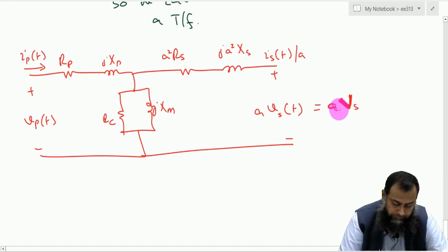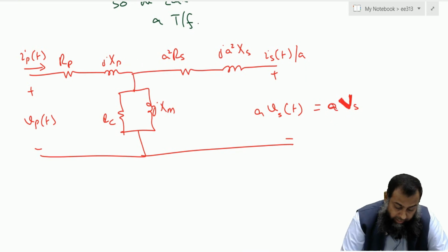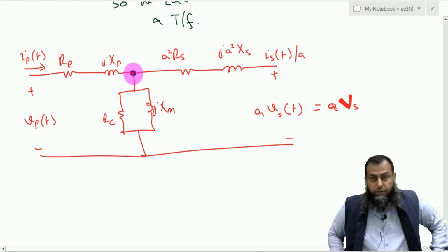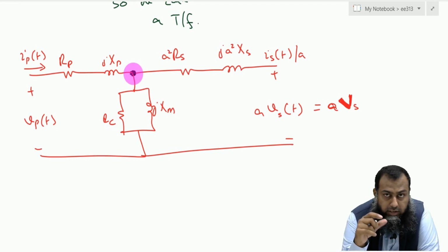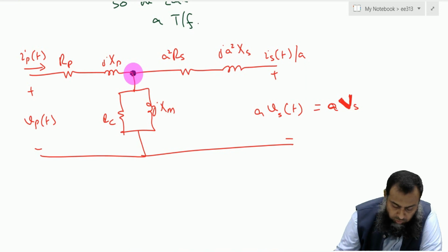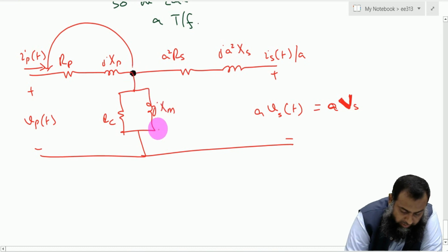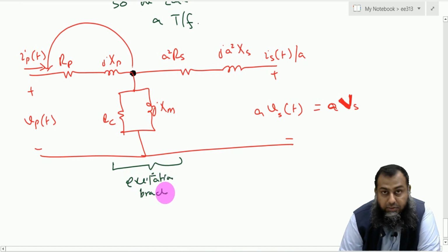If you see here, this equivalent circuit has an additional node here. If we do not have this additional node, then we may actually add the resistances in series and the inductances in series. So one way of having an approximation is, we shift this particular branch, which is known as the excitation branch, onto the extreme left side, right?